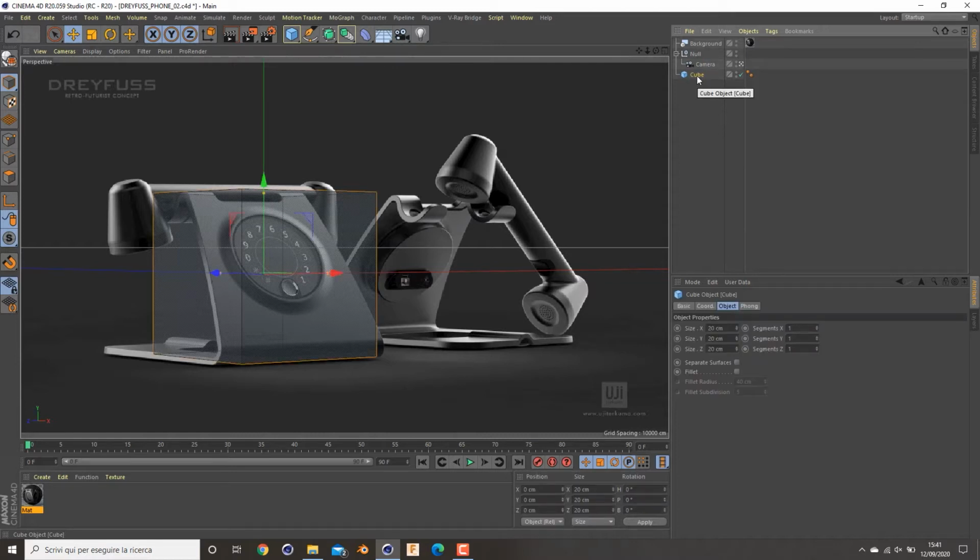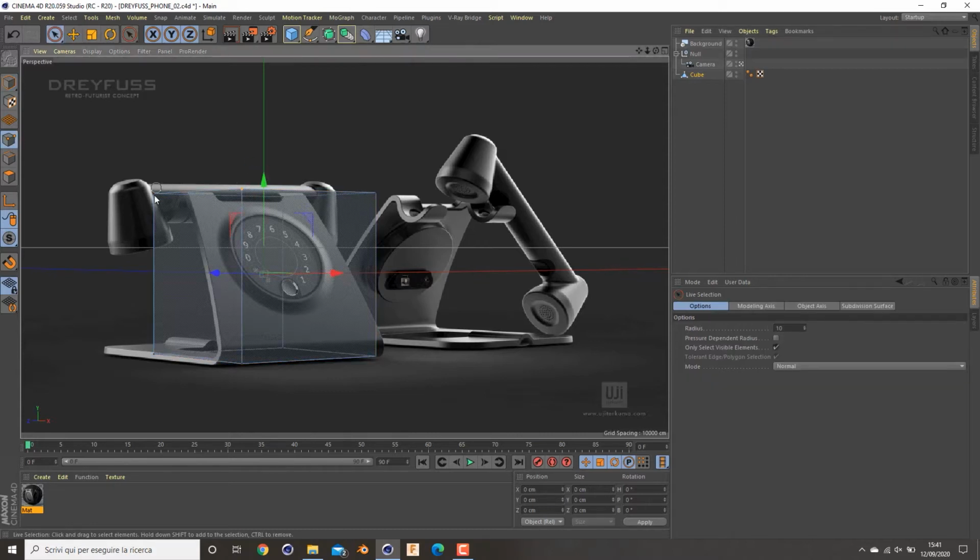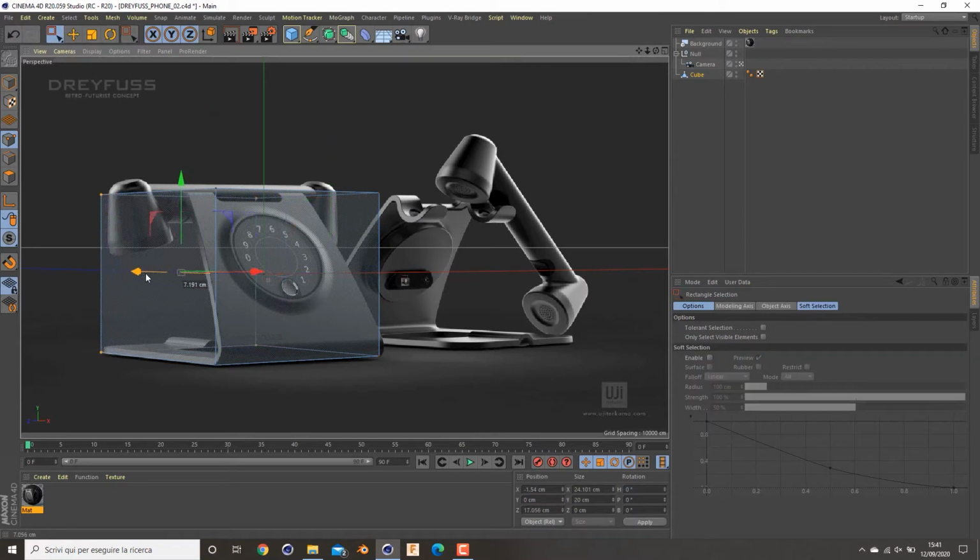First of all, make the cube editable by pressing C on your keyboard. Now start to select your points on the cube and move them to roughly match the size of the font on your image. To create the basic L shape of the model, just delete the backwards points and start moving the front points into position and scale them properly.